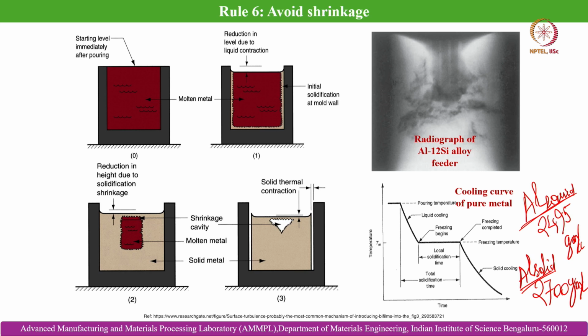The most dangerous and critical shrinkage, responsible for defect generation within the cast objects, is the solidification shrinkage. It can be mitigated effectively by positioning risers.